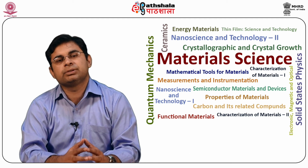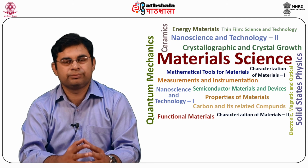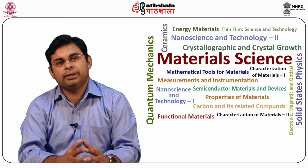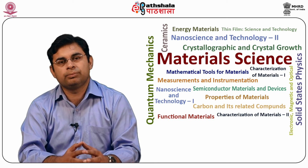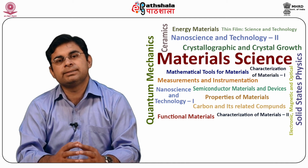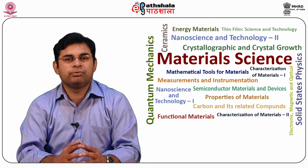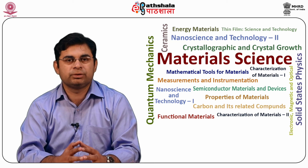This completes the outer shell of the load cell structure. Finally, the upper lip of the top diaphragm and the central column is welded to the top diaphragm. This seals the inner portion of the load cell, which makes it impervious to gases and moisture.